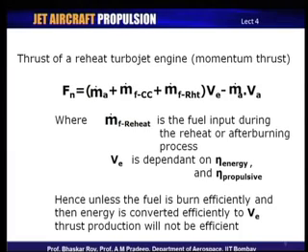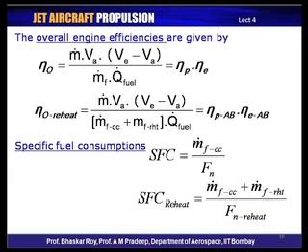And this is something which an engine creator or designer would have to bother about right in the beginning while putting together all the components of a jet engine. The overall efficiencies that we had talked about, we can take a quick look at them again. And now we have the overall efficiency, which is of a basic jet engine multiplied by the propulsive efficiency multiplied by the energy efficiency, and this is something which we had defined before.